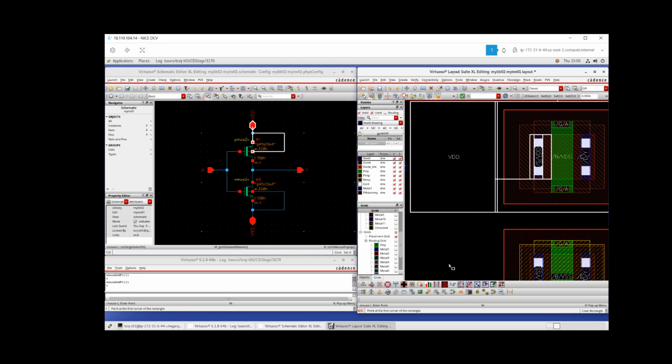And we know that the endwell for the PMOS is the body, so it labels it as BDD because in the schematic we already connected that to BDD, but we don't have the physical connection yet.